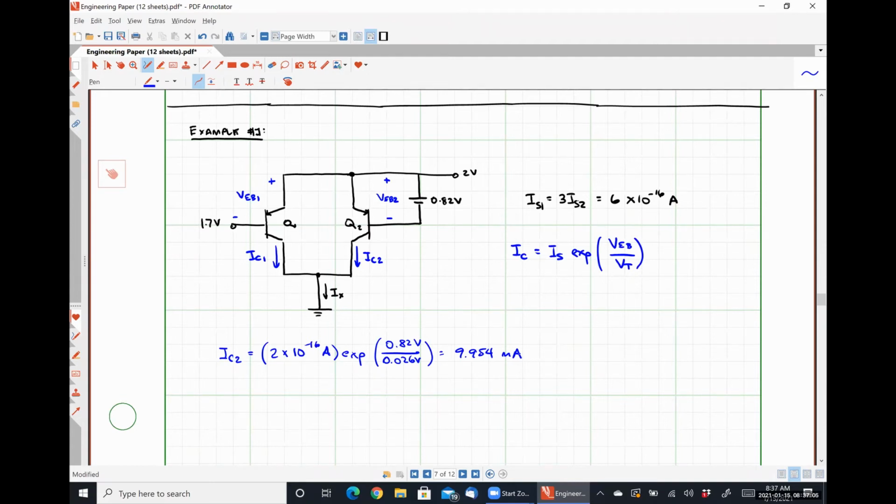What I thought would be the common mistake here is that most people would say, that's the voltage applied at the base, so that's VBE or whatever, and get that confused with VEB, which is different. Because our emitter is tied not to ground, which is unusual for us, I feel like that's a pretty common mistake. So I just wanted to watch out for that. Good job catching it.